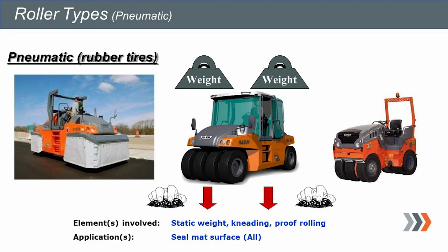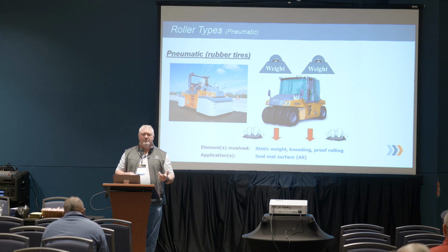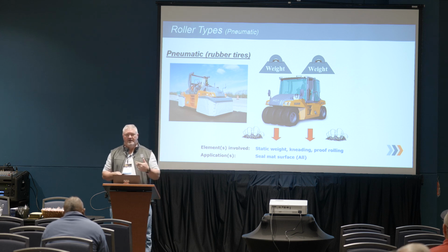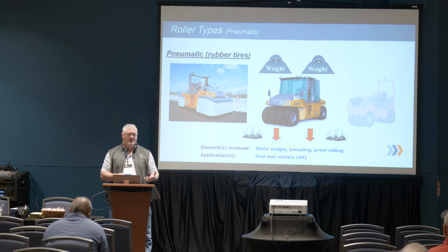Rubber tire rollers, we talked a little bit about there. Another key thing to remember about rubber tire rollers is heat. We want to make sure we maintain that heat in the tires so we reduce the amount of pickup and reduce the amount of additives that we're going to have to put on the tires. The more additive you put on the tires, the cooler you get, the more stuff you end up picking up.